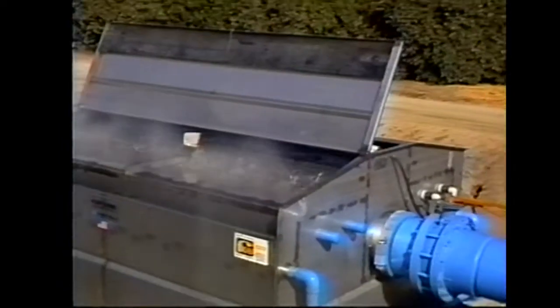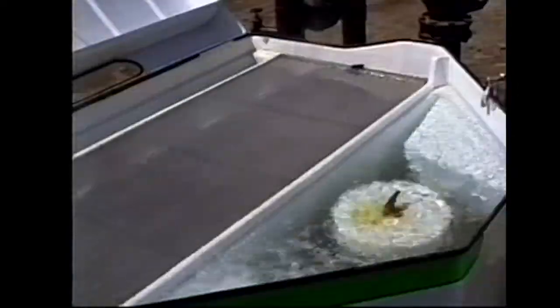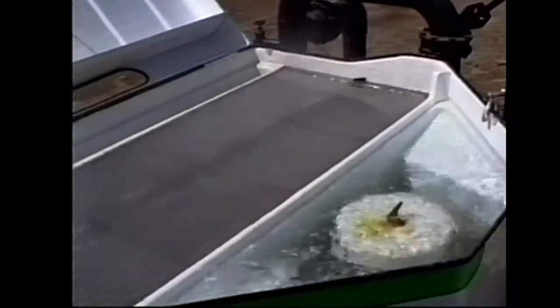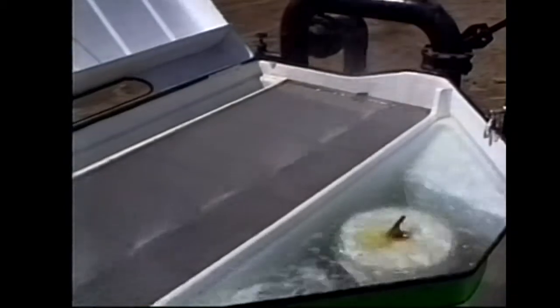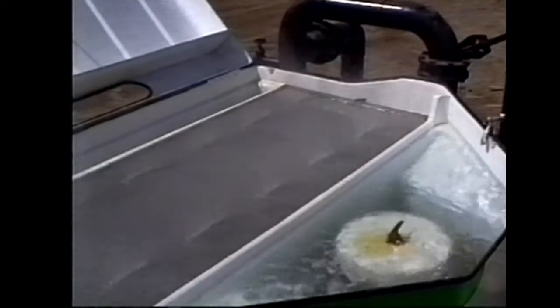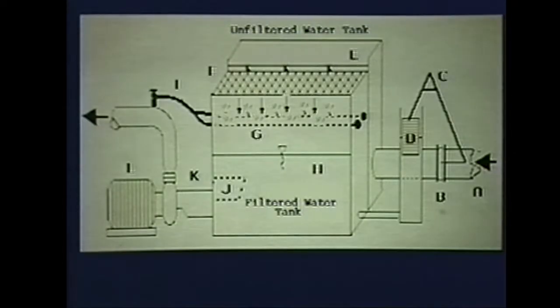Gravity overflow screens are popular in some areas. They provide high-capacity filtration for organic and inorganics. Water enters a tank and then flows over a weir onto a tight screen which is slightly tilted from horizontal. The screen is typically 150 mesh and is underlain by stainless steel expanded metal for support. Clean water passes through the screen to a collection chamber where it is picked up by a booster pump and passed onto the irrigation system.